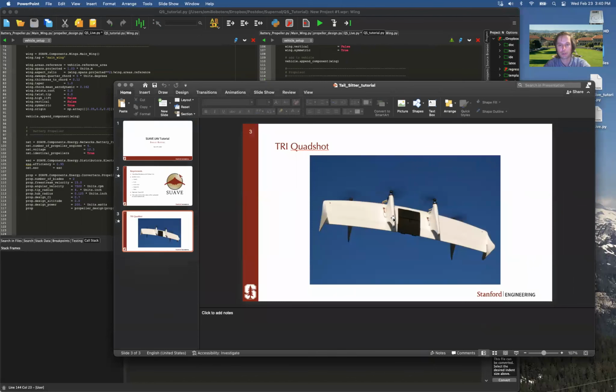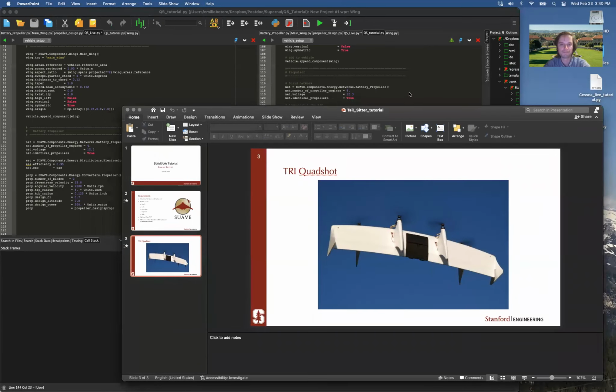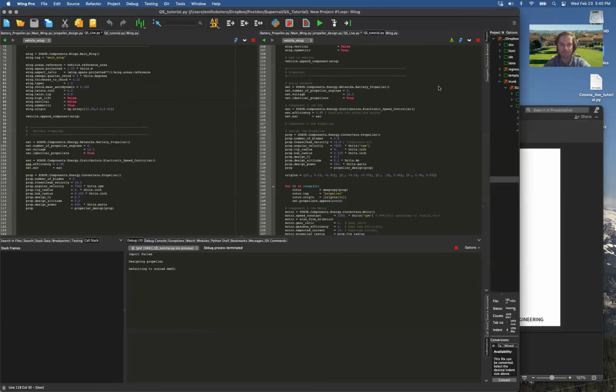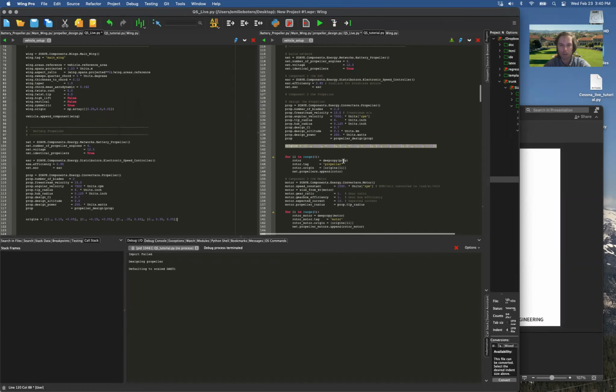So these are the motors here. This is the bottom side of the vehicle, and they're about 15 centimeters, half a foot, 6 inches up from center line, and a few centimeters off center in the Z direction. So this is the bottom of the vehicle. And then similarly for the outboard ones, they're a little bit further out, but in the positive direction. So that's what these origins mean. And we'll add them here, and then we'll loop through.